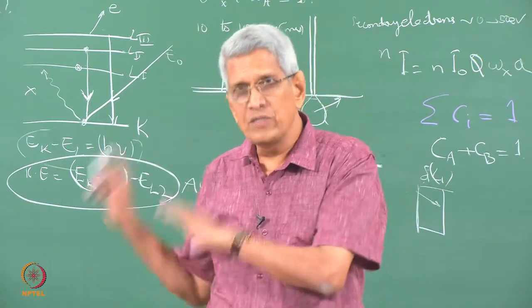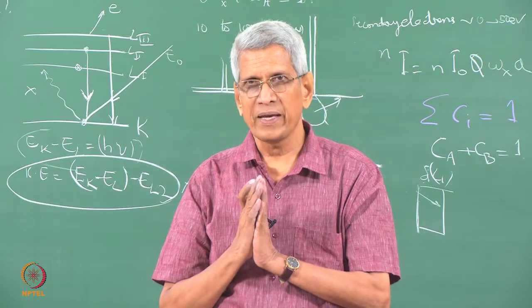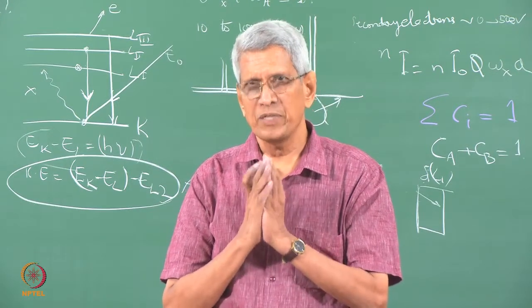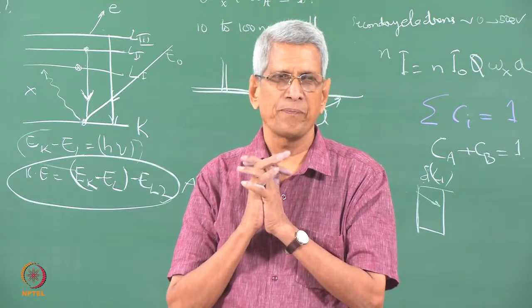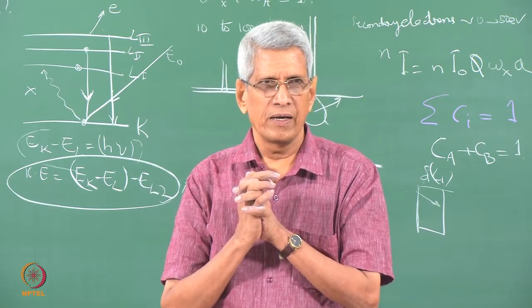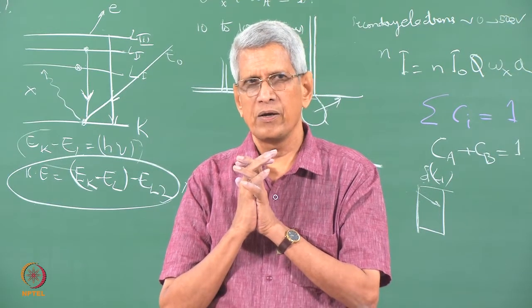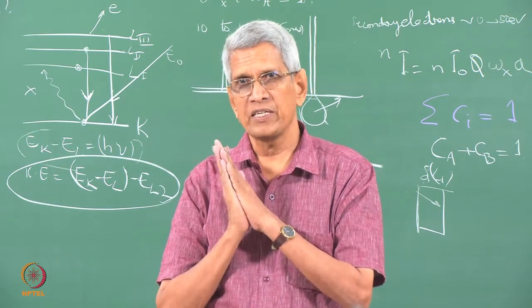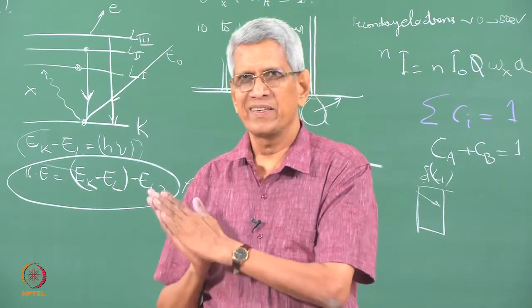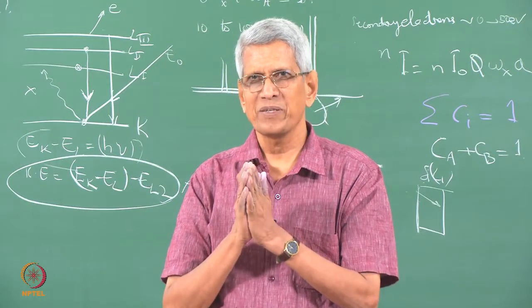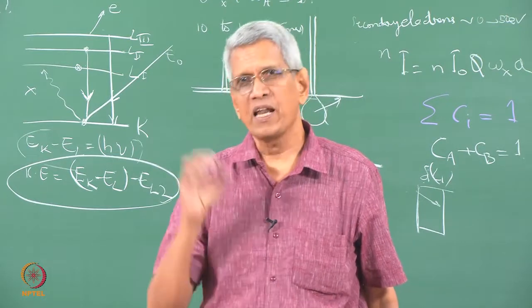Then this also determines the peak to background as well as the peak signal. That is going to determine the minimum detectable fraction. Whereas in many of the wet techniques, such as optical emission or atomic emission spectroscopy, we can detect with much greater accuracy, down to ppm levels, but that is not possible here. Here, at best, if we can do 1 atom percent to 0.1 atom percent, that itself is considered great, but for that we have to take a lot of precaution.